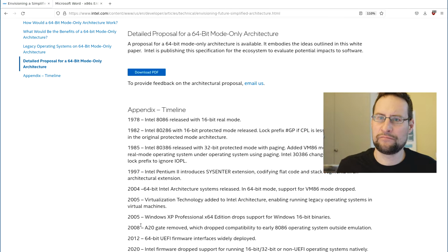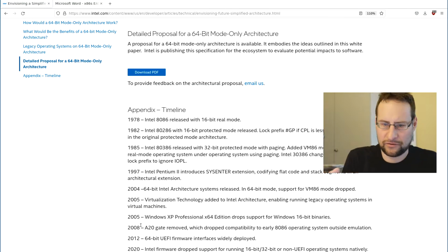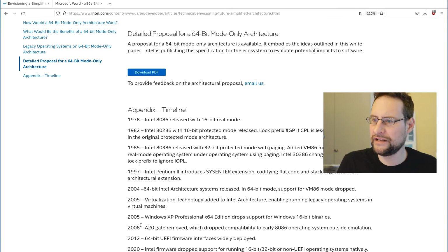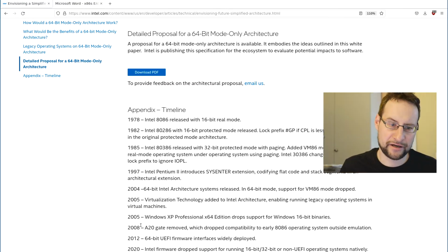Having the already super complex x86 with this complexity, yes, it's not that much, but it's adding up, right? And the decoder is already the bottleneck, and the x86 instruction decoder, with variable length instructions of 1 to 32 or so bytes, has to be implemented and take care of this kind of legacy.